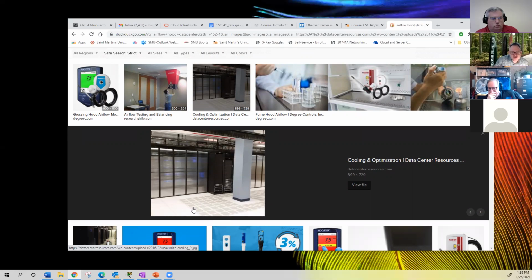But there's no server cabinets around. They're here, but it looks like that's a plexiglass back end. So in this case, cold air is being blown up into the room from under the floor, and it's doing nothing. It's just blowing up in the room in the data center, and it's not serving any purpose. So part of utilizing your cooling effectively is to remove and cap with just regular tiles.